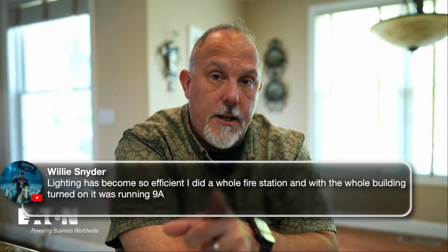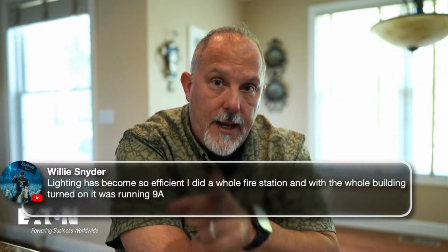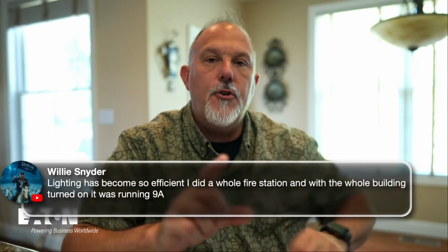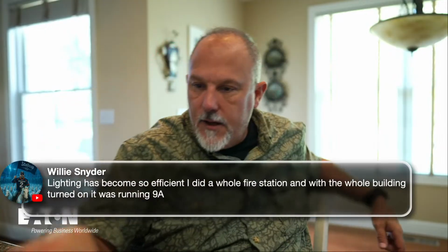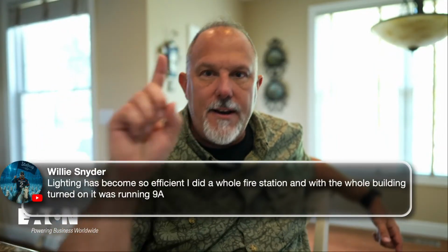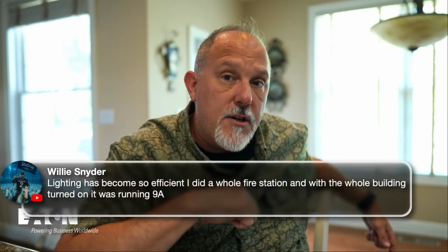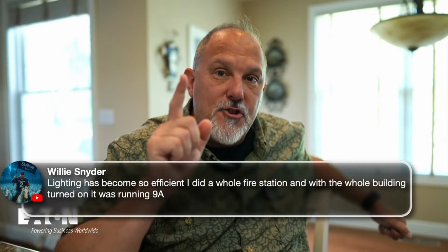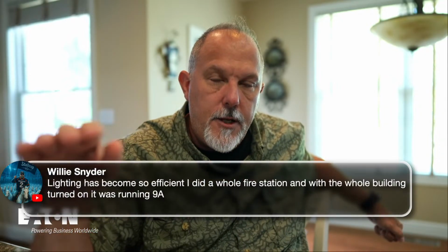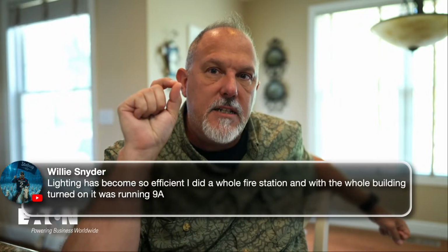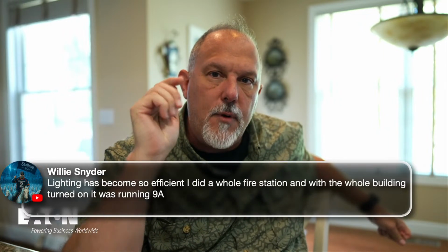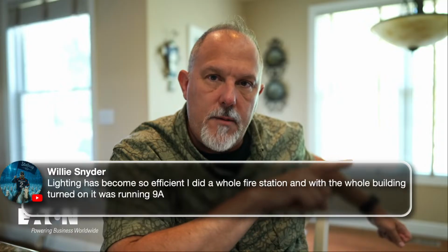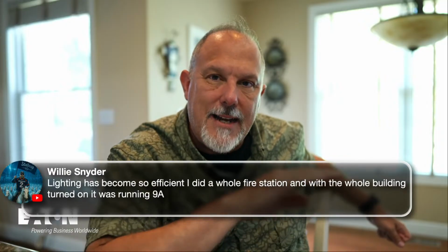Now, here's the challenge that you will create. You won't create an ampacity issue. You won't create a termination issue. You're going to create a challenge of, I can put everything, you have all the lighting on 9 amps. So you could put a 15 amp circuit breaker to cover all of that lighting. But if that breaker trips, you lose everything. So what you would then have to make a decision on is, how do I break up my branch circuits in a way such that if I turn that one breaker off, it doesn't kill the entire building.